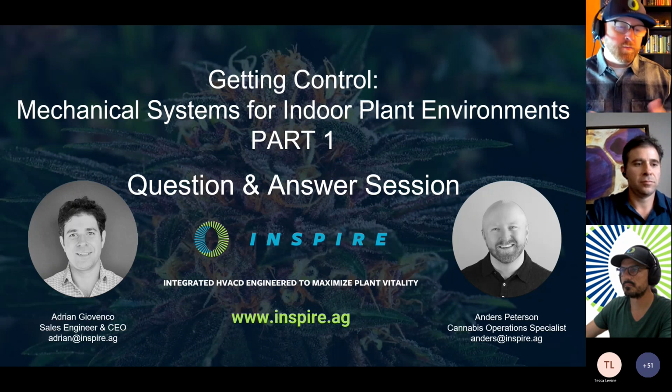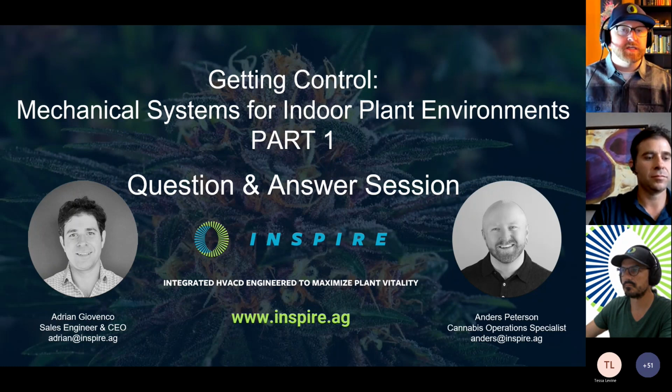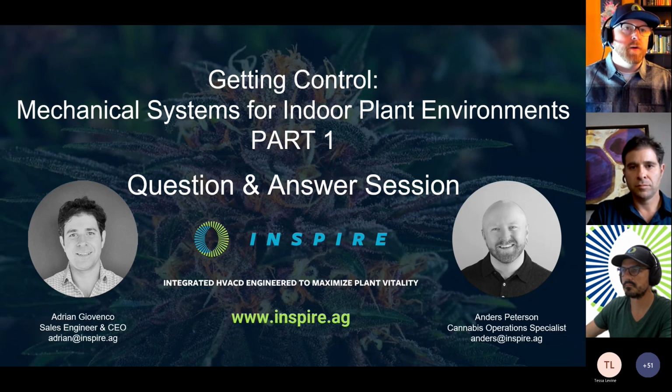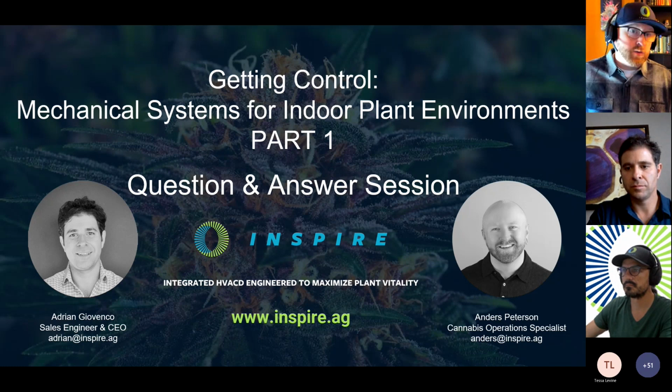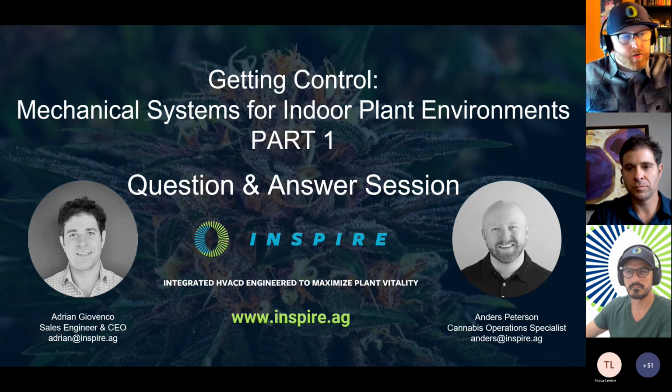And then having a number of those throughout a room to get an average and run your systems at is much better than operating off of, say, a thermostat that's built into a mini split hung up on the side of the wall. I mean, the conditions on the side of the wall are not what I'm trying to control. I'm trying to control the canopy. So that's where I want my sensors to be.